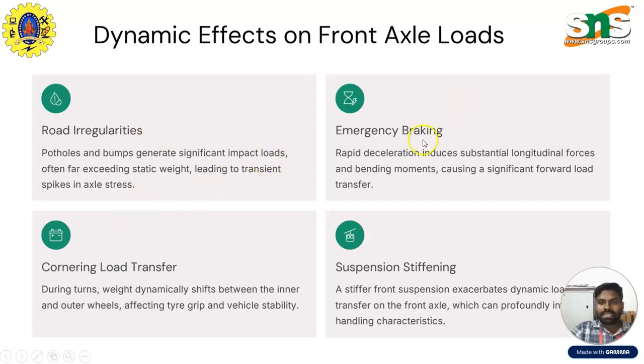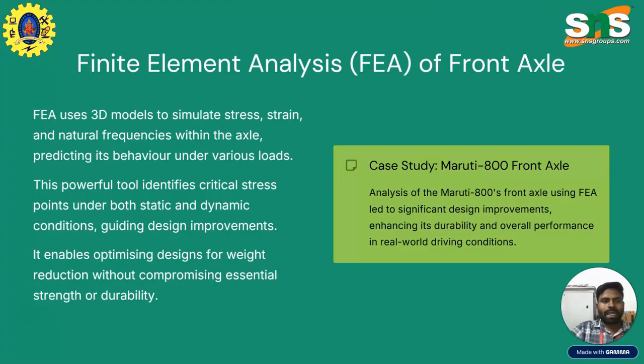And then emergency braking and cornering, load transfer, and suspension stiffness. So these are some additional factors that have an impact on the front axle loads. And as I said earlier, we have to design the front axle while considering these factors.